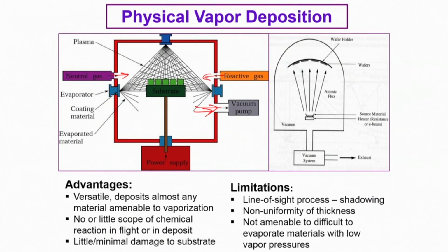But this is not very regular or usual, but feeding argon is fairly regular, because once you evacuate, then when you feed in argon, argon remains neutral, and it also creates a situation whereby undue oxidation is avoided. So this is the substrate, the component that you want to coat, or maybe this is the stage, and on the stage you can place multiple components, like here 1, 2, 3, 4, 5 components.